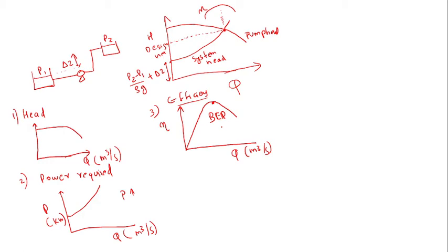Usually a knockout pot is placed before a compressor to remove unwanted particles from the incoming stream. Like if some unwanted particles like water droplets enter the feed, they can be separated using a knockout pot. It is a vertical drum.